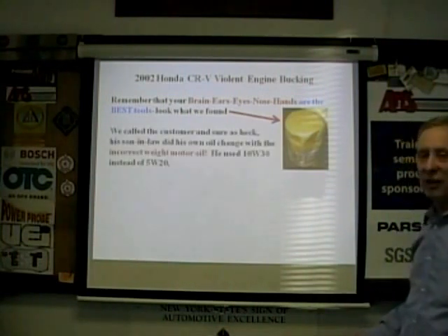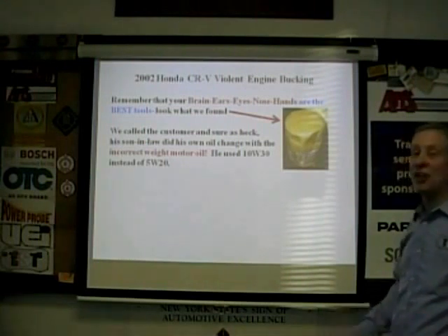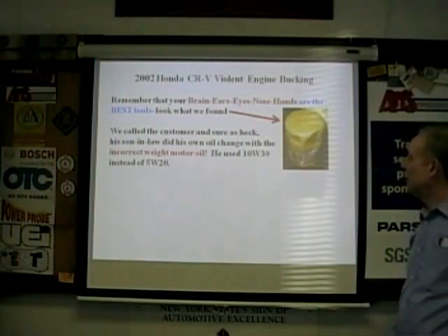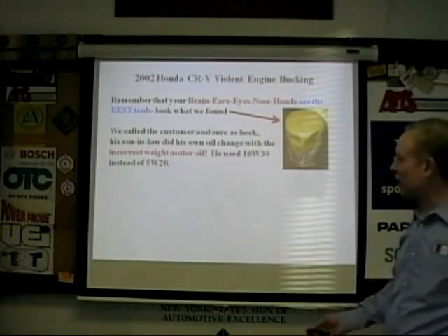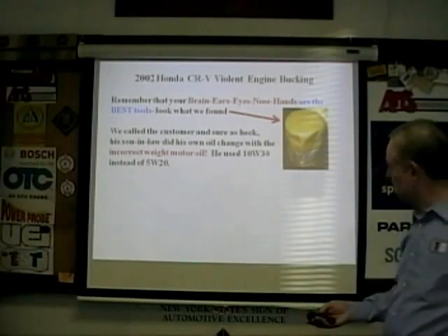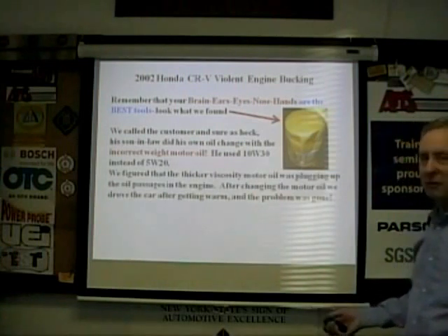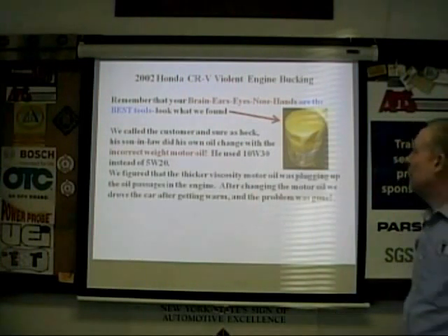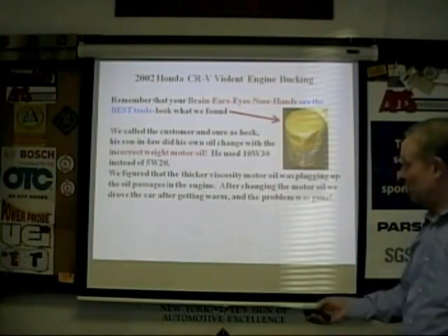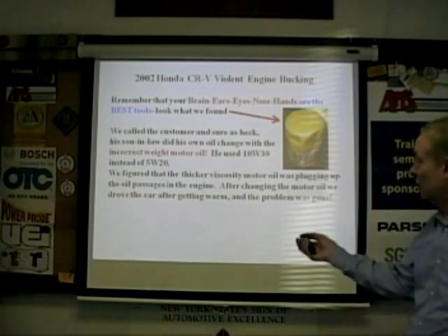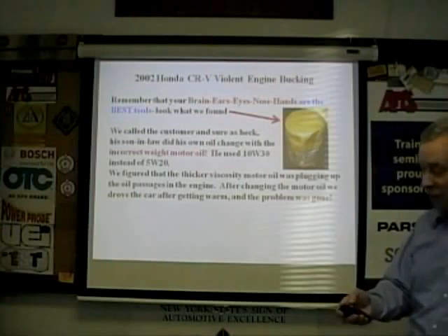They called the customer, and his son-in-law had changed the oil and put in whatever he had on the shelf. You know, it's all good. It's oil, right? So the difference, you mean just that 10W-30 to the 5W-20 can cause that? Absolutely. And it can cause bigger problems because in a cold start situation, it might starve for oil.